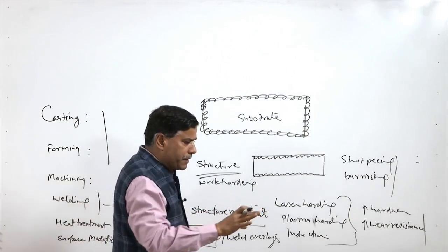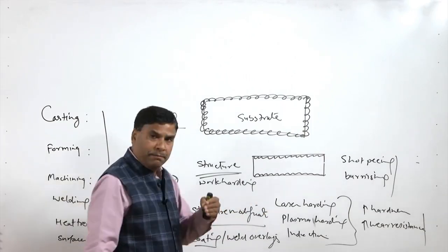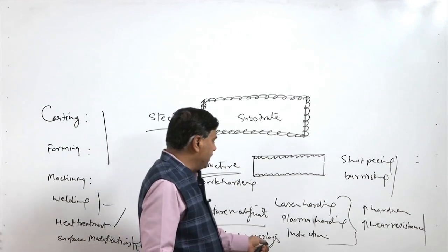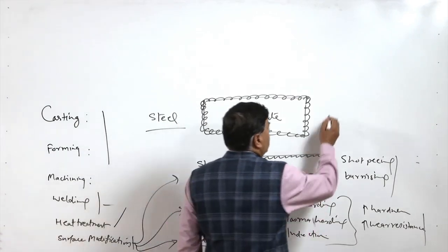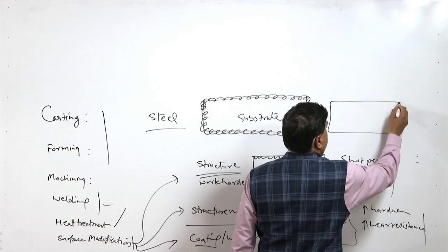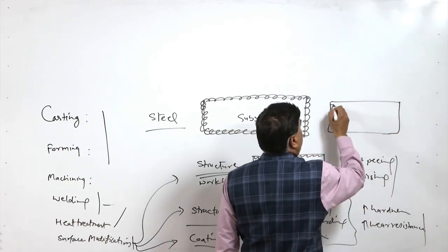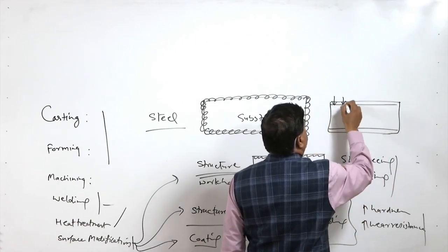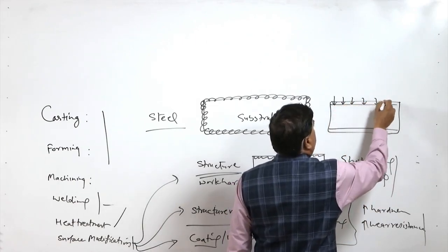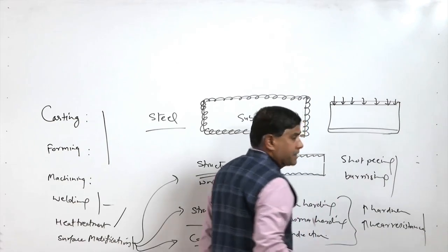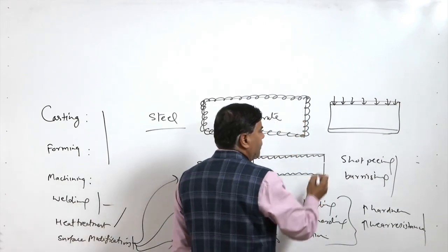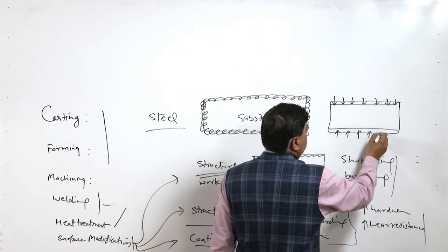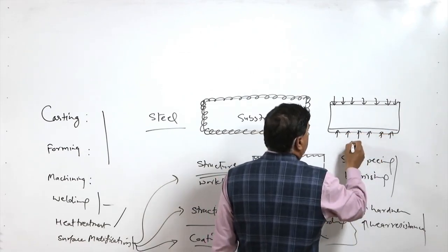So, basically surface properties are modified by applying the material having suitable properties in the form of coating or weld overlays, and sometimes certain elements are diffused onto the surface. Like if the carbon content in the steel is low, then carbon is diffused in carburizing, so that martensitic transformation becomes easy for hardening purpose. Similarly, for nitriding, nitrogen is induced, so iron nitride is formed, which is harder.